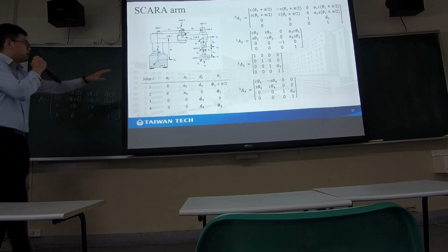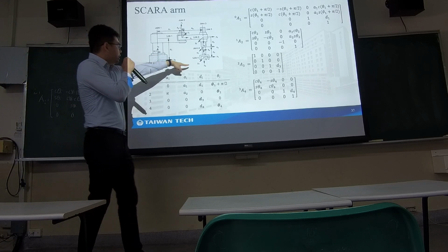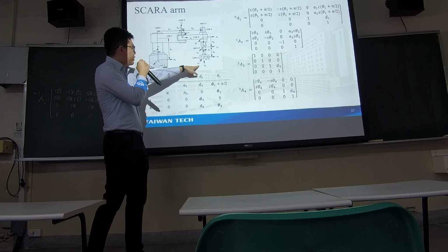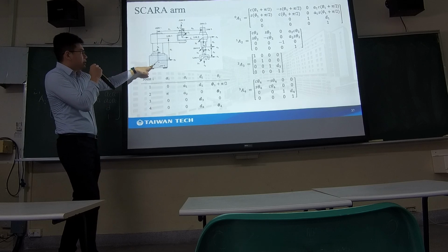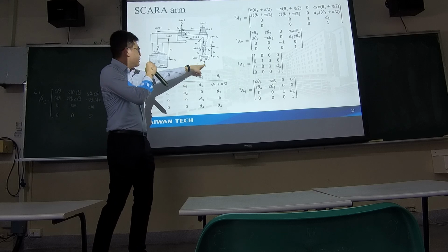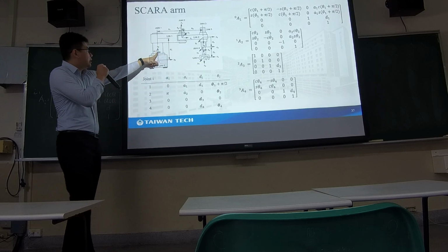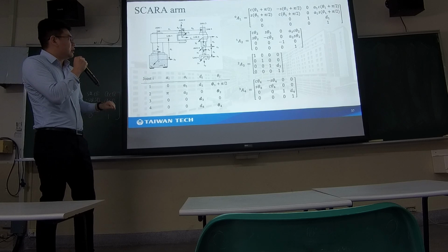Then we can compare with our settings. So in the end effector configuration, the y-axis is the same as our x-axis, and the x-axis is the same as our y-axis, and z is just a minus, so it's reversed.